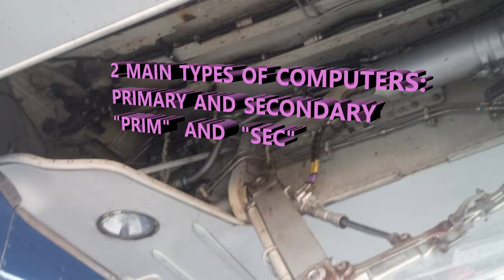Okay, so that's giving you kind of a helicopter's view on the flight. When we talk about the primary flight control system, that's what it is: your computers that I just mentioned, the primary and the secondary, abbreviated PRIM and SEC, and all the control surfaces except for the slats and flaps.